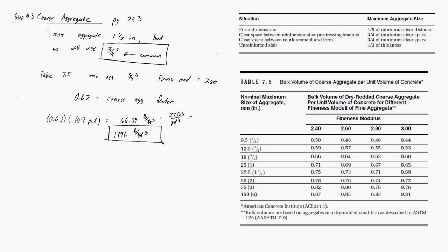In our case, with all the spacings I gave you, our maximum aggregate size would have been 1.5 inches, but we're going to use number 57 stone, which is a fairly common stone, which has a maximum aggregate size of 3/4 of an inch. So this will obviously fit, but it's important that you make sure that your aggregate fits into whatever you're going to pour.